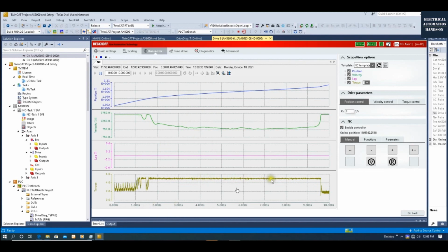This highest torque set point will depend on the tension, the highest tension from the web. And the speed can adapt according to the mainline speed. So we can set a torque set point and allow the system just to do a rewind, and its actual speed can adapt. Okay, this is the MC torque control from the Beckhoff NC axis.